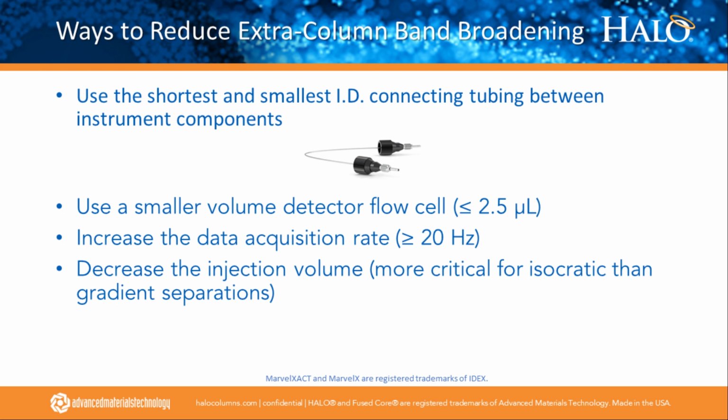So I have a picture here of a Marvel Exact connector. These are finger-tight zero dead volume connectors that we recommend. I know there are other sources of zero dead volume connectors. Part of the reason that we like these is the design of these connectors: when you tighten them down, it's not possible to over-tighten them because after they're fully tightened, you both hear and feel a click. So I think that's a nice part of the design of these connectors.